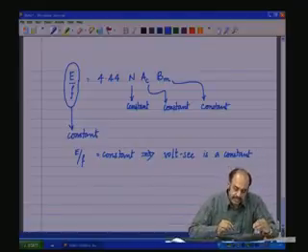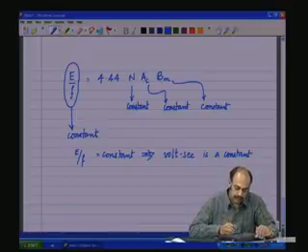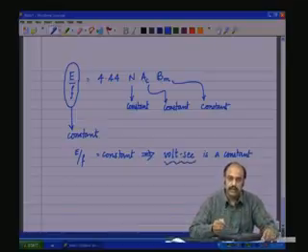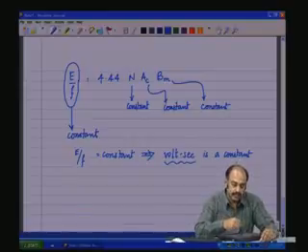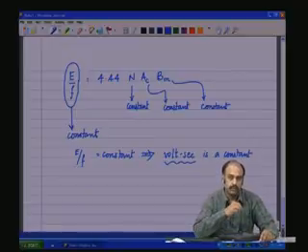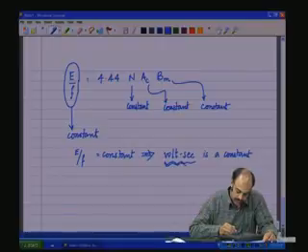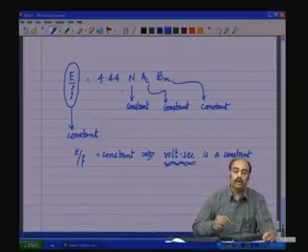So, one has to design for a volt second product in the case of the transformer such that the maximum flux density in the core, Bm, does not exceed B sat for that core. That is the important conclusion that you should draw from this modified equation.